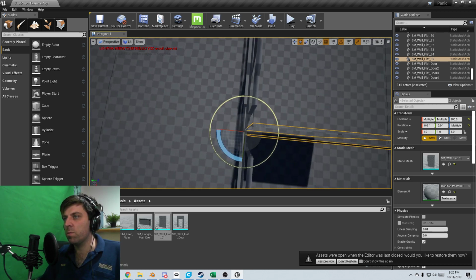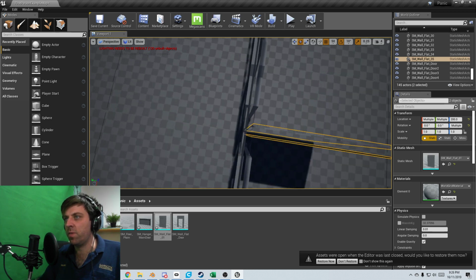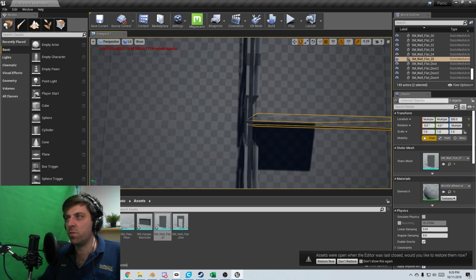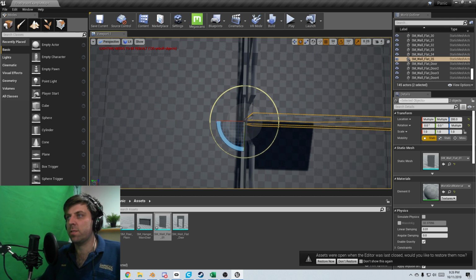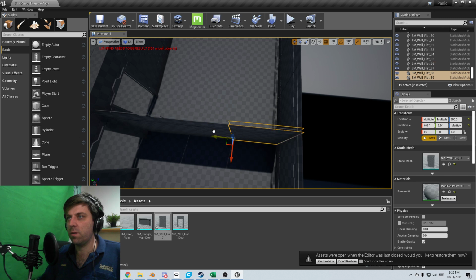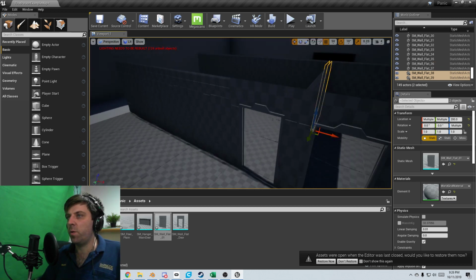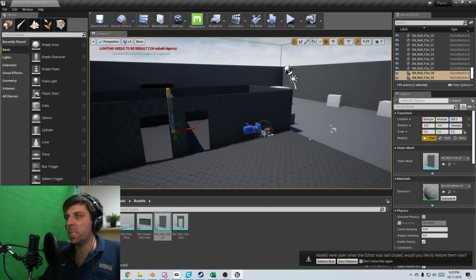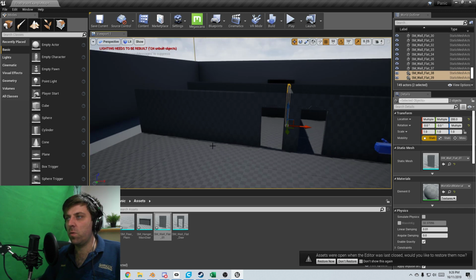Now, as I was talking about before, how I offsetted it. So with these walls won't be coming in. So even though this wall finishes on a 0, it won't actually protrude on the other side because the walls are offset. So that's just something to keep in mind. There we go. Done. So now we've got separate rooms. I need to create some sort of walkway.